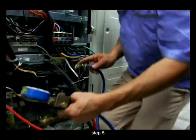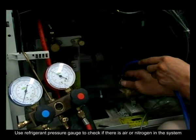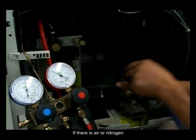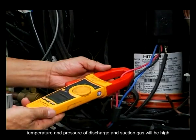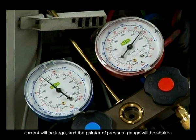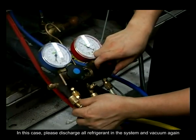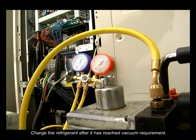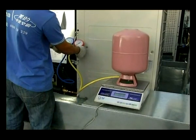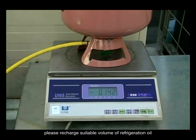Step 5. Use refrigerant pressure gauge to check if there is air or nitrogen in the system. If there is air or nitrogen, temperature and pressure of discharge in suction gas will be high. Current will be large, and the pointer of pressure gauge will be shaken. In this case, please discharge all refrigerant in the system and vacuum again. Change the refrigerant after it has reached vacuum requirement. If refrigeration oil goes out during the process, please recharge suitable volume of refrigeration oil.